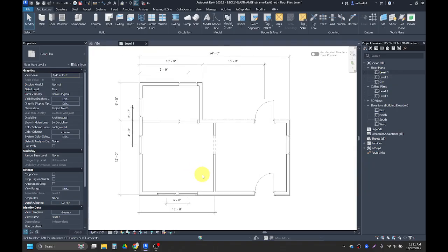There are a couple of different ways you can make a floor. The way that I like to do it is create something for my entire floor system first. That's just going to be my joist and subfloor. And then I create smaller floors that are kind of hovering above different areas in the building, of just the finishes. So that's kind of just my preference.